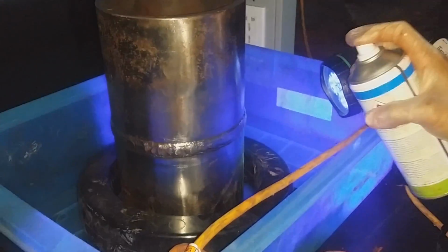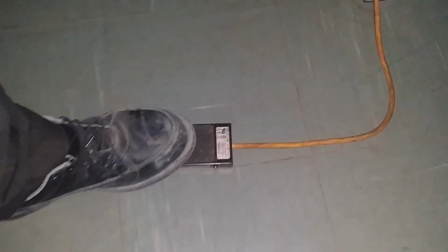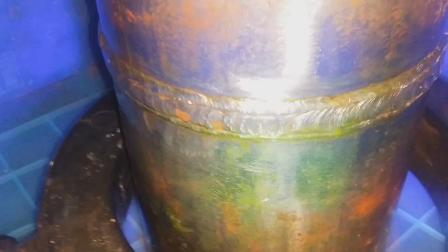It is better with pipes, as follows. Plug the power cord of the coil into the appropriate outlet. Depress the foot switch. A magnetic pull will be felt by insertion of a ferrous metal object into the center of the coil. Inspection is accomplished by placing the part longitudinally parallel to the axis of the coil, within the coil nearer to the outer circumference. Activate the foot switch and apply the inspection medium while the coil is energized.